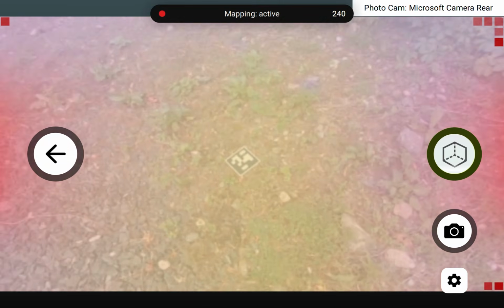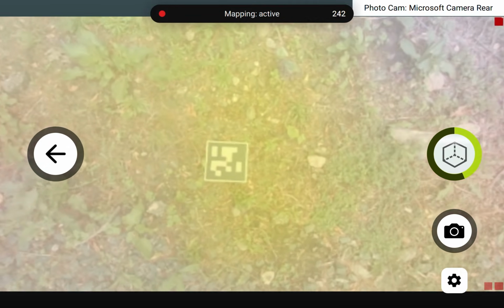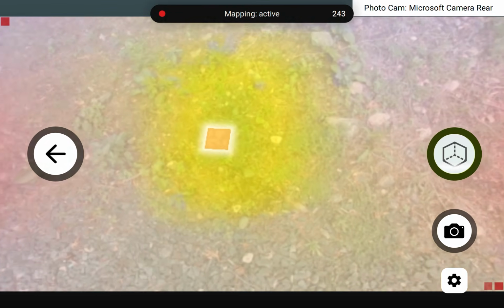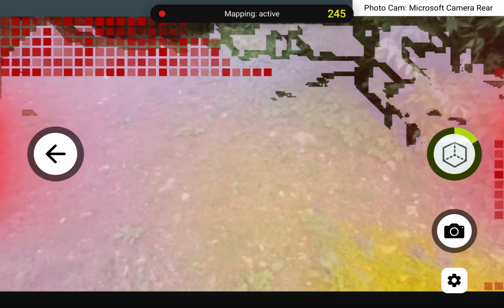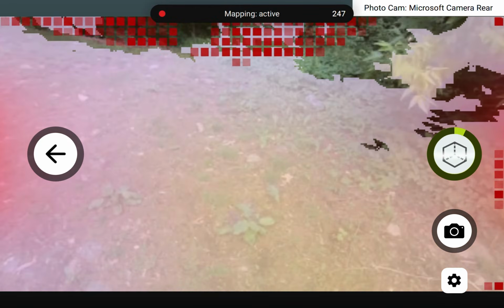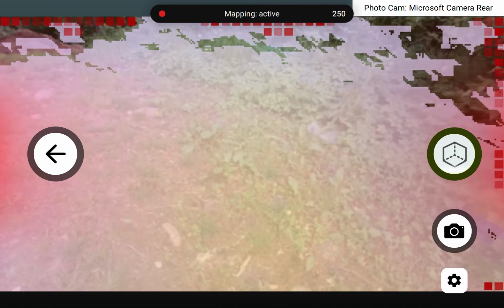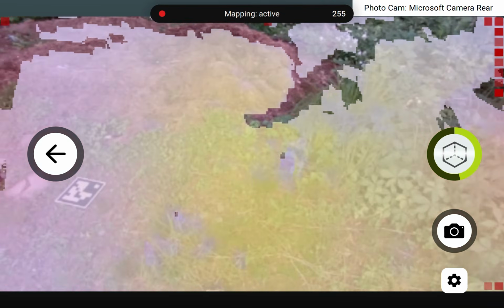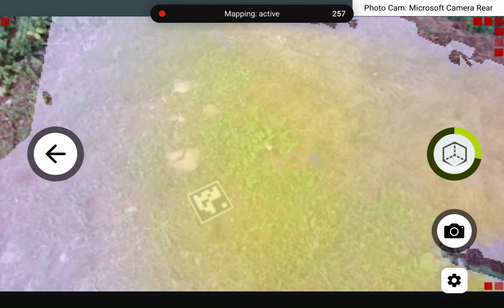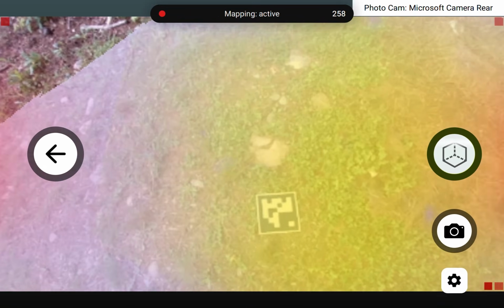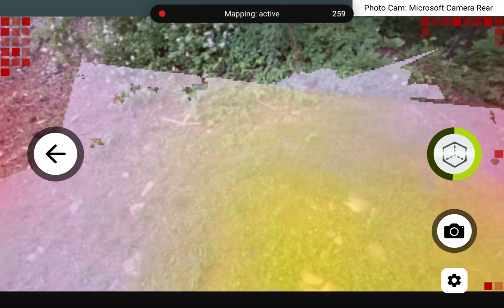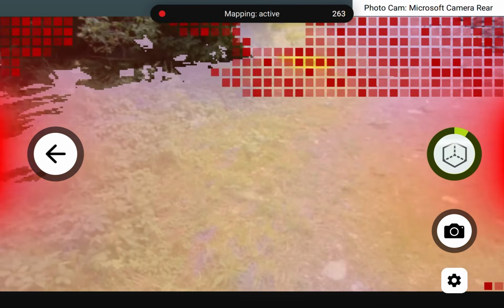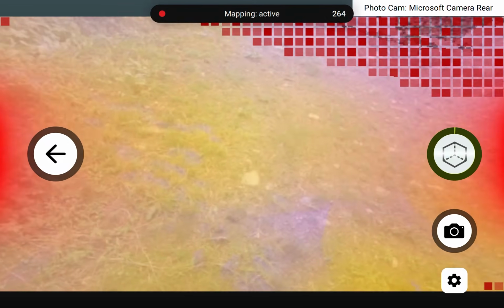There certainly can be more challenging tracking situations when scanning outdoors, so you do want to make sure to take your time, be patient, and if you do lose tracking, just back up to regain it. When you're scanning along buildings, texture, indoors, things might be a little bit easier, but flat white walls can also present their own challenges. So in general, you want to follow geometry in your scene, panning along the edge of a floor wall intersection, for example, before backing up to fill in the more flat, empty spaces.